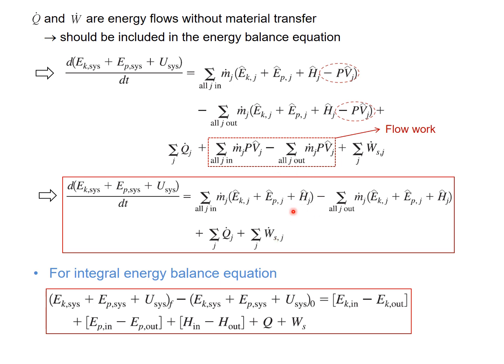Please remember, you have internal energy for the accumulation term. However, in the input and output flow term, you have enthalpy. So please memorize it. Again, internal energy for accumulation and enthalpy for the input and output flow term.